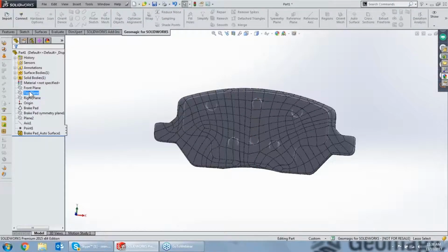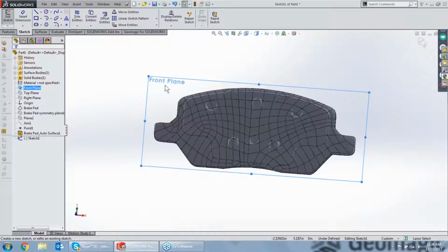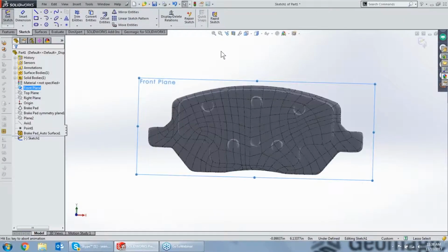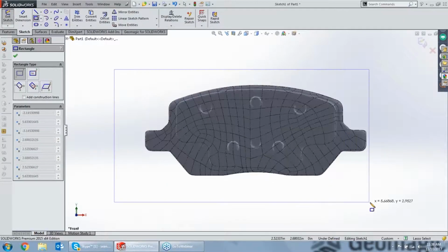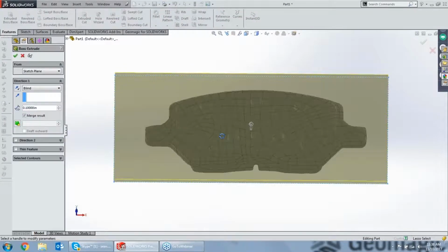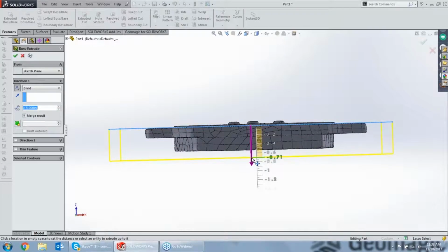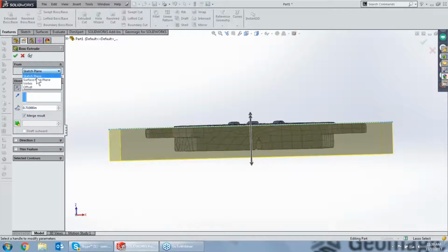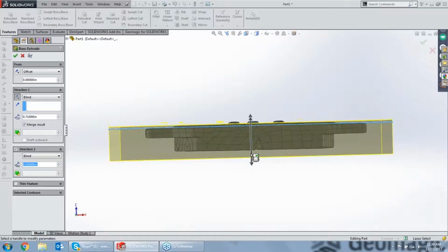If I took one of these planes here, for example, this guy, and I did a sketch on top of it, I'm just going to create a very basic body that we can remove this CAD from. So I'll just grab a rectangle tool here very, very quickly, exit my sketch and extrude. I'm going to be extruding that in the opposite direction here. And I'm going to just offset the starting point of that extrude. I don't think I can.